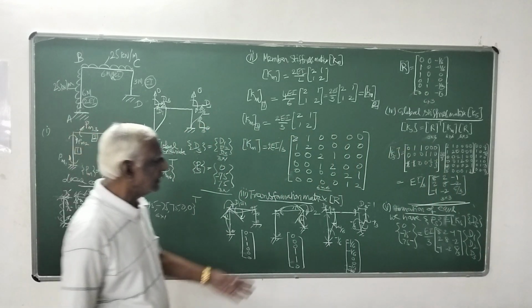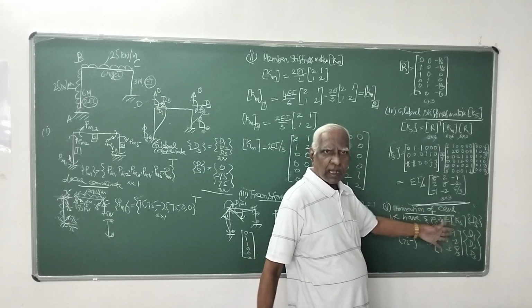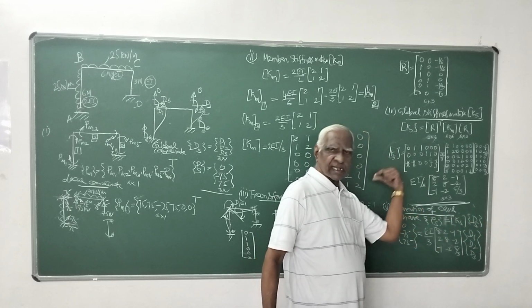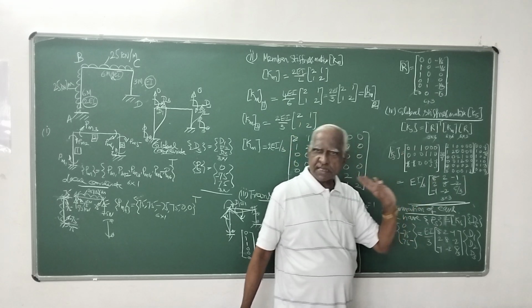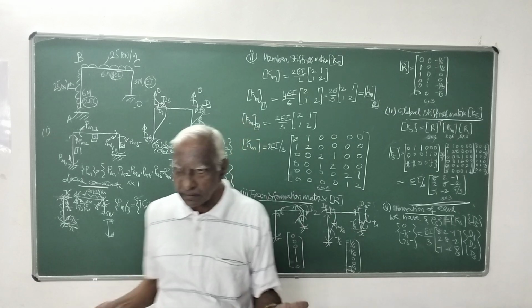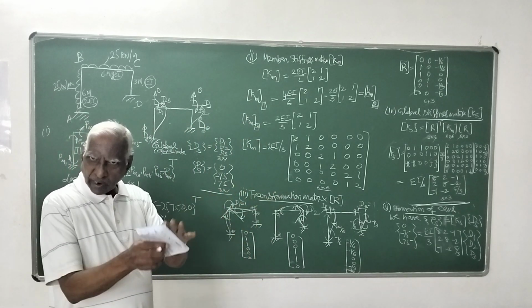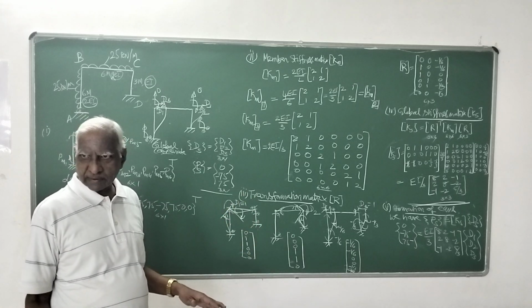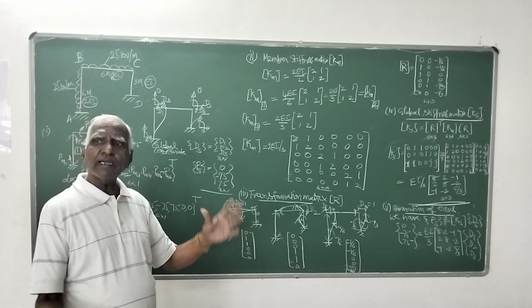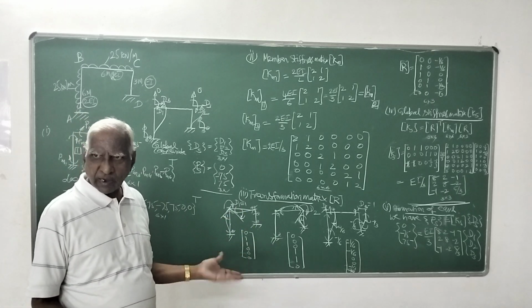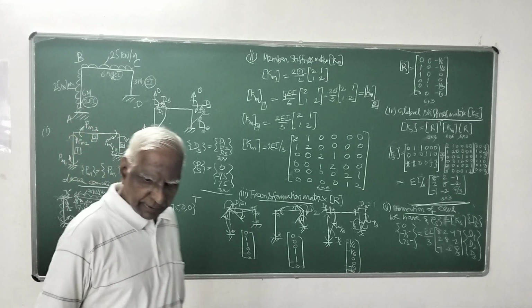This equation you can solve either as simultaneous equations, or you can invert the Ks matrix and multiply by Ps to get the displacement. Whichever is easy, or if the computer program you are writing has a solution equation solver, you can use that. Otherwise, in MATLAB, you just invert it. So that is your next step.